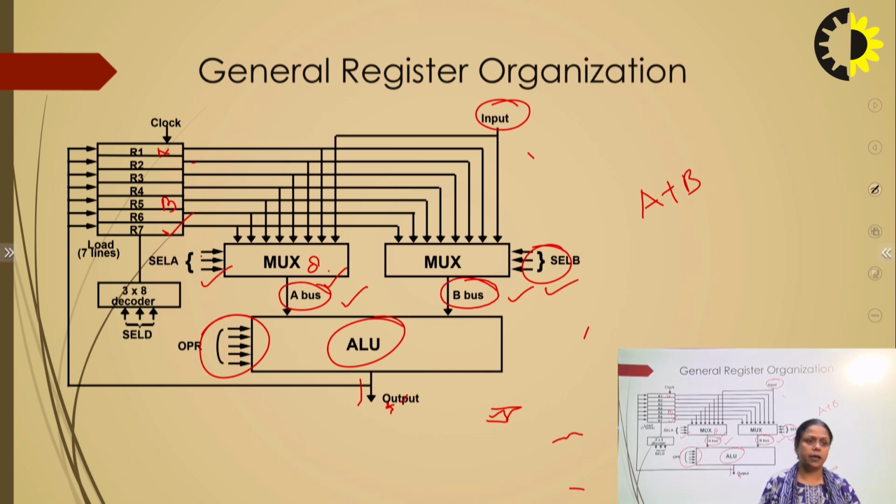So, we can see here the ALU will perform only the operation, but the overall control of the operation is held by the control unit. In this case you can understand the major role of the control unit. These operations, for example, the input for the ALU, the selection lines for multiplexer A and the selection lines for multiplexer B, are all provided by the control unit only.